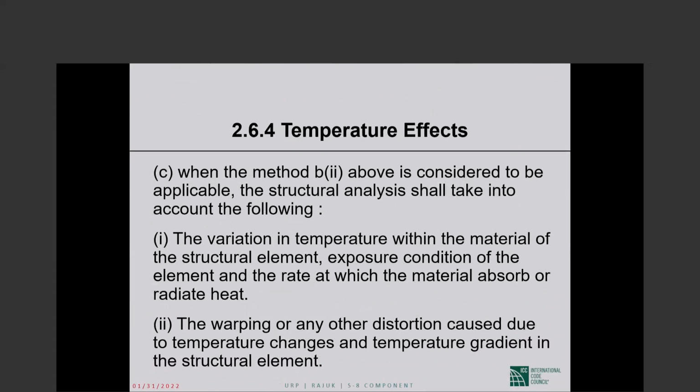When the second method is considered, you will calculate essentially the loads due to temperature differential. When the second method is considered to be applicable, the structural analysis shall take into account the following: the variation in temperature within the material of the structural element, exposure condition of the element, and the rate at which the material absorbs or radiates heat, the warping or any other distortion caused due to temperature changes, etc.